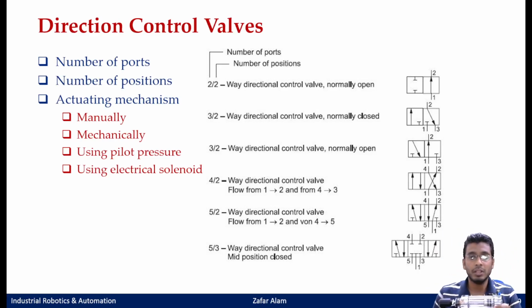Okay, so in this single acting cylinder, if you see, there is one port for extension. When this is a pressurized port, and when this cylinder retracts, what happens? Your fluid has to drain from this and has to come back to your tank port. If I say tank, I am actually referring to your hydraulic circuit, and if I say atmospheric air, I am actually referring to your pneumatic circuit.